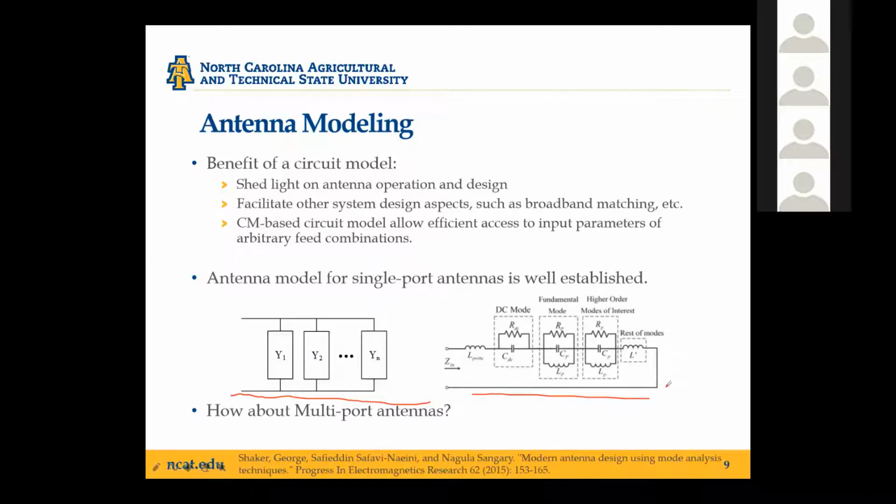As I mentioned earlier, with characteristic mode analysis, you can always reconstruct the antenna response with just one characteristic mode calculation. So if you develop a circuit model for an antenna, it facilitates calculating the input parameters on the antenna aperture for any feed locations and any excitation combinations. I think that saves a lot of effort in terms of simulation for different feeding schemes on the antenna, for example.